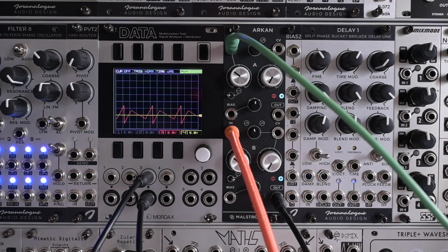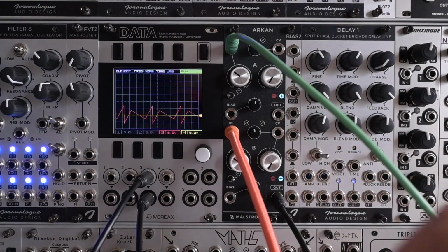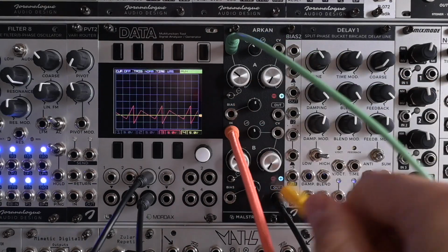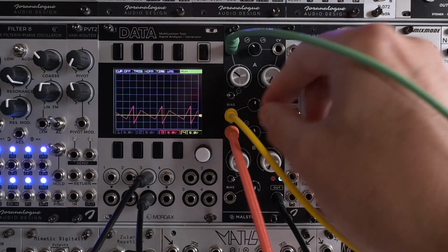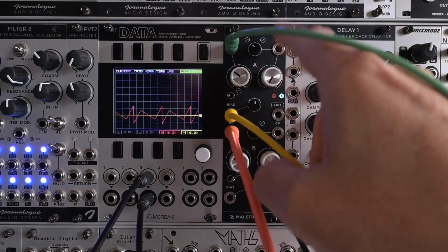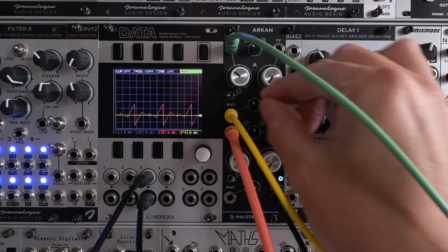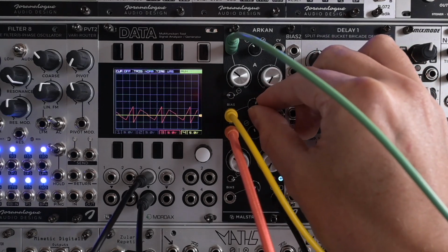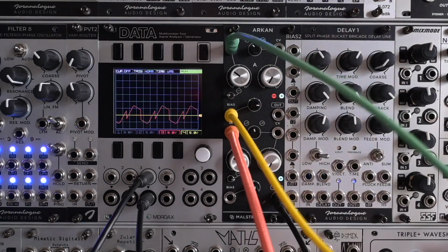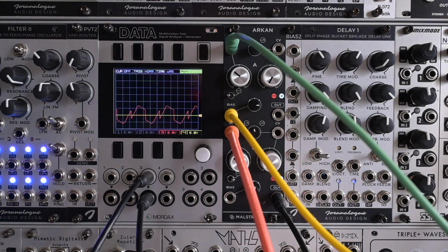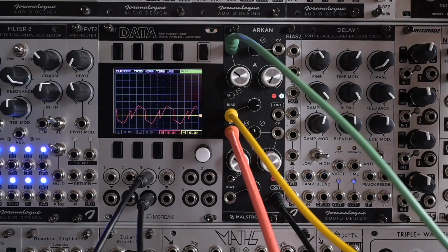Now you can send in more signals. Let's take a square wave. So you can send in 2 more signals to the bias inputs, because this is essentially just getting mixed with the top channel here. And you can set the volume and even the inversion with this bias attenuator. And since there's another one of those here, you can mix in a 4th signal.